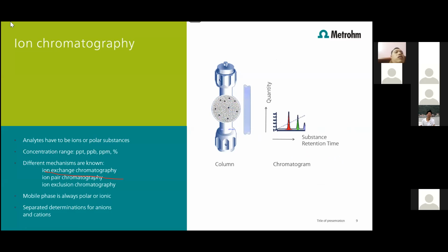In ion chromatography, the ionic compounds go through the column, and the separation takes place in the so-called stationary phase. To pass the stationary phase, every component of the sample needs a specific time, relative to the flow rate and the type of eluent. This time is called the retention time.